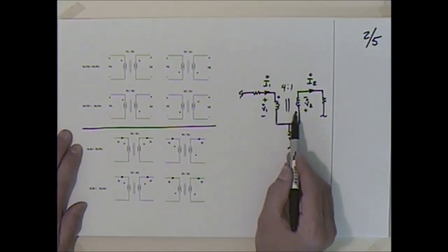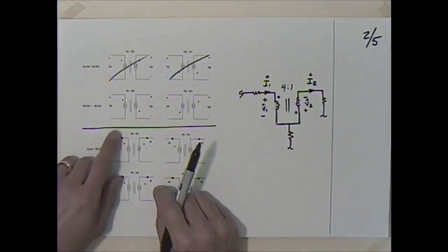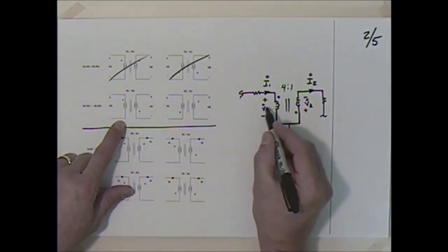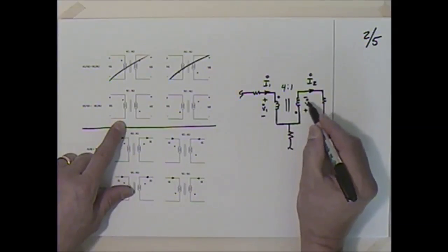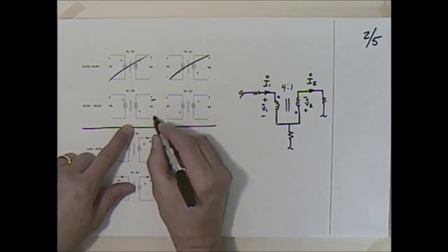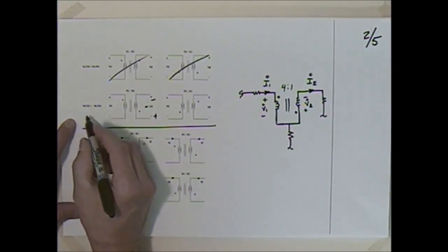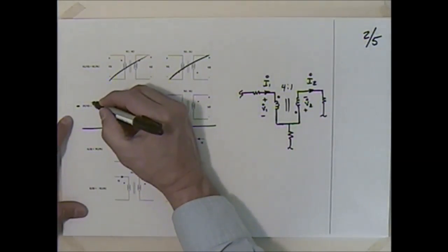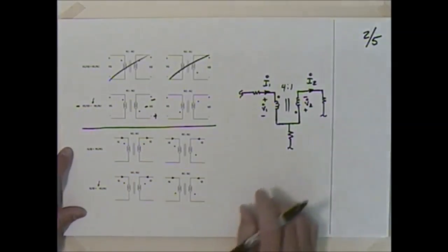In terms of the dots being alternated, this one's not going to do us any good. That one's not going to do us any good. It looks like this one has the dots alternated, so I like that one. V1 is positive, negative here. Our V2 is kind of upside down, or opposite in relationship to this. So if I put a negative here and a positive here, I could just put a negative in front of that, and we would then have a minus V2. Well, remember that we already have a negative right there, and a negative right there. So effectively, we've really just canceled that.